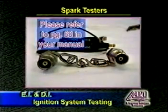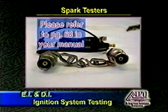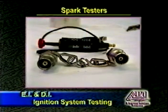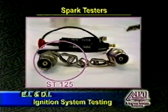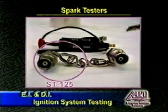Now, most technicians will use a spark tester, especially on EI type systems. But what you have to understand is you're looking at 3 different flavors, or 3 different types, of spark testers. The spark tester in the lower left-hand corner is what we call the true ST125, meaning that it requires 25,000 volts to fire. If you were checking the vertical calibration of your scope, a good idea would be to use a true ST125 spark tester to check that.